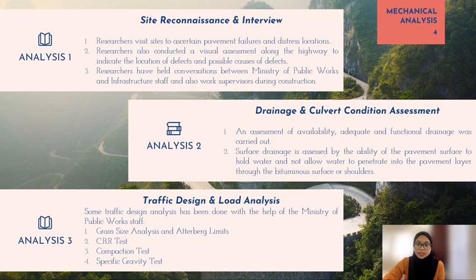There are three analyses that have been done by the researchers. First analysis is by site survey and interview. Researchers visited sites to ascertain pavement failures and distress locations. Researchers also conducted a visual assessment along the highway to indicate the location of the defects and the possible causes. Researchers held a conversation with the Ministry of Public Works and Infrastructure staff and also work supervisors during the construction. The second is drainage and culvert condition assessment, an assessment of